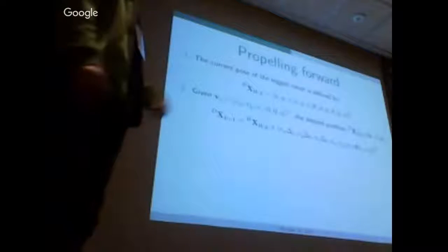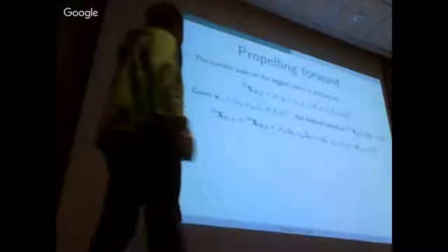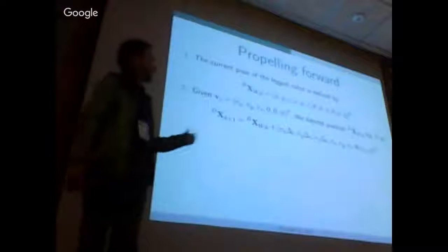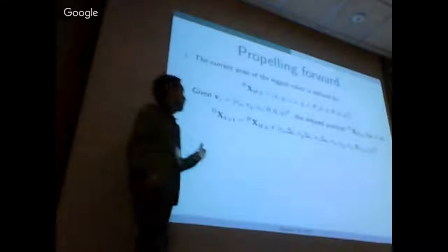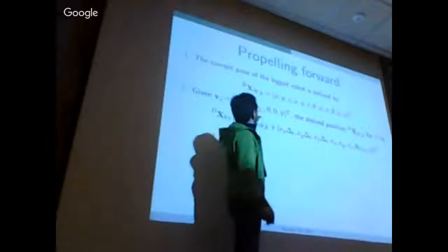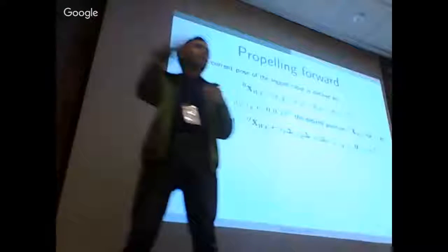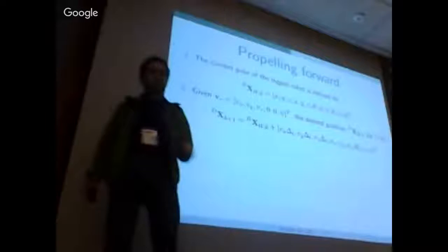So given this, the velocity vector and the velocity command, the desired center of mass adds an integration from the initial state. The velocity components are multiplied by delta t, so we get a delta x, a small displacement, and it is integrated with the current state of the vehicle.